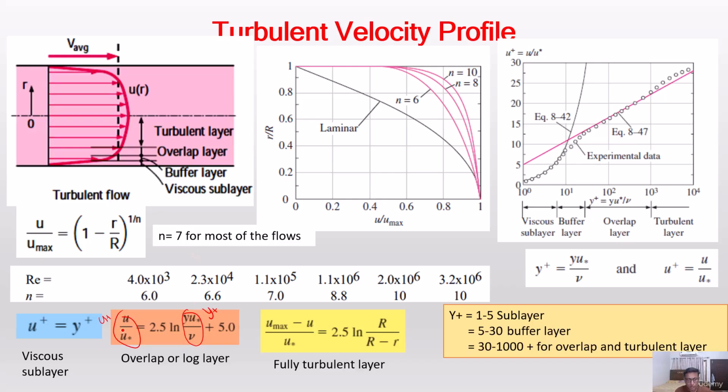So to solve this through CFD, this is implemented in the software. We don't need to select it ourselves. If you are solving with the wall function, then this equation will be activated. And if you are solving with y plus equal to or less than 1, then this equation will be implemented. So how is this implemented? Actually, this is a mesh.